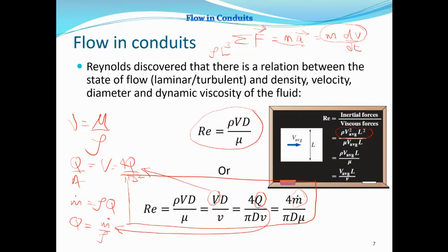And then for the acceleration, we have the velocity over time. But don't forget, we can divide this into V times L over t, and L over t, that is distance over time, is also velocity. So we have rho L squared V times V, which is rho L squared V squared. So this is the inertial force from Newton's second law of motion, ma.